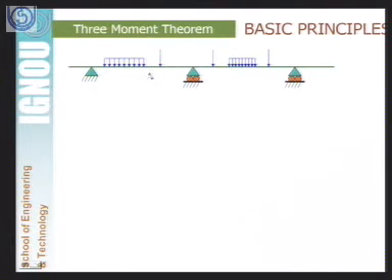So if we want to analyze this continuous beam, one of the methods is that let us make the beams simply supported and release the moments at these nodes, and then after releasing the moments at these nodes we can apply the unknown moments at these nodes and find out the effect.